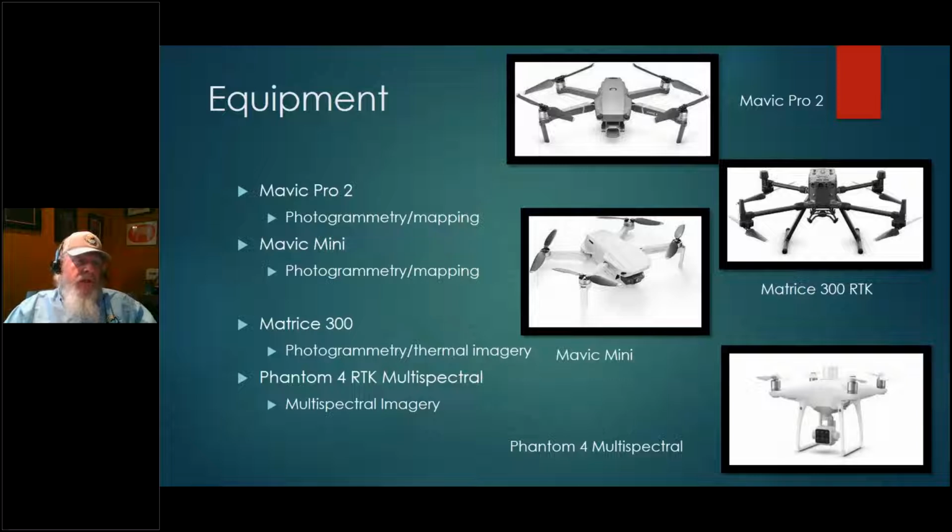For instance, we're using it in our dam safety program to try to determine if there's leaks in some of the dams that we're surveying with this photogrammetry, because we can tell the difference between the soil temperatures and the water temperatures, and so we might be able to see where there's a leak coming in and at least let us get there without having to walk the whole dam or spend hours trying to find a small spot. We can do it in just a matter of a few minutes with some of this information.